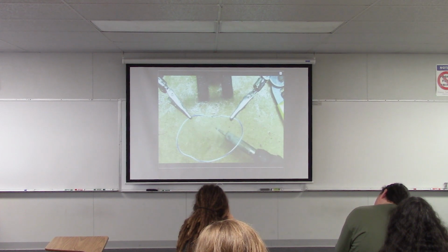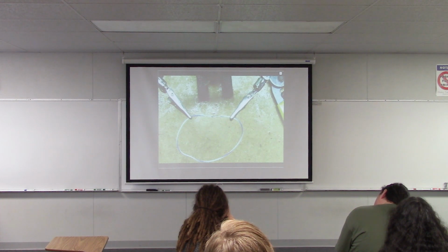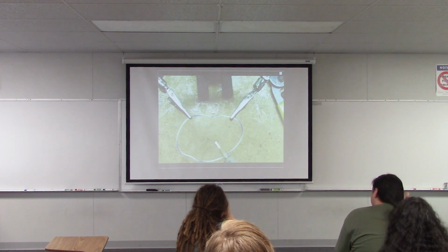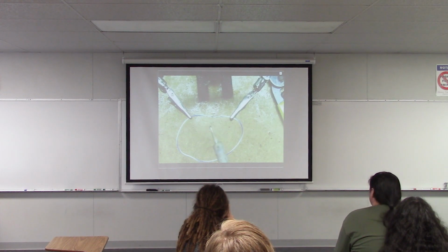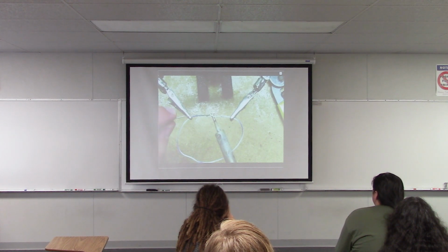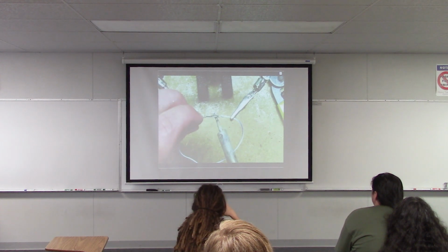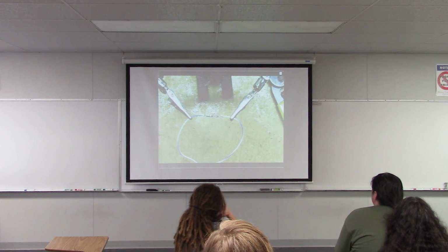And you can see it starts to smoke. That's the flux that I was talking about. And this little drip of solder on the end of the iron helps to conduct the heat from the iron to the joint. Now once we have this drip, we're going to put the iron on one side of the joint. In this case, I'm coming up from below, and I'm going to count to maybe 5, and then I'm going to come down from the top, and I'm going to start painting the solder all over the joint where I want it to be. So you just paint the solder in there until it kind of covers everything, and then you move the solder away and move the iron away, and that's your solder joint.